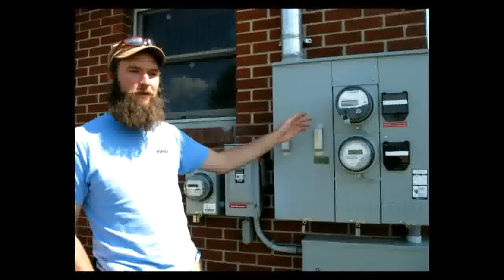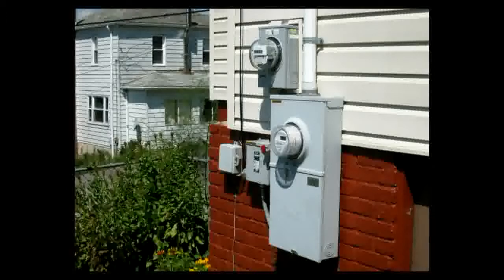With this system being a commercial system, we had to do a special, it's called supply side tap, meaning the service conductors over here are tapped in this long trough, and that is what the PV is feeding back to. And this is different from how a typical residential installation is installed. A typical residential installation, the power that is produced by the solar can be fed back to a breaker on the homeowner's breaker panel. And it's a little easier, a little more straightforward to do it that way.